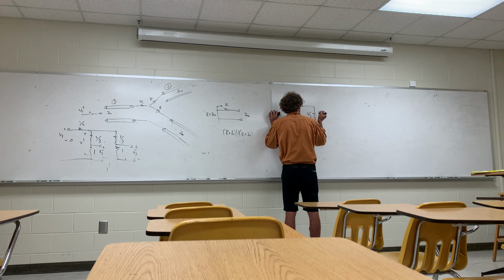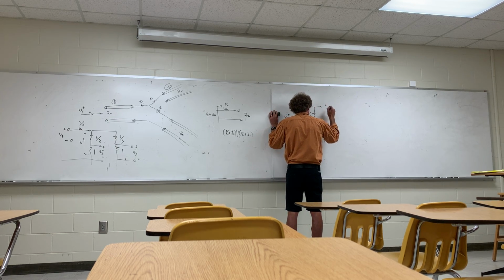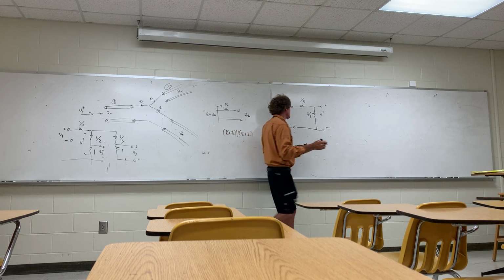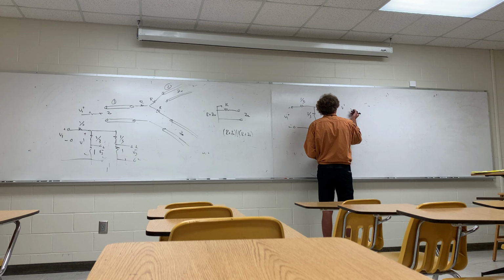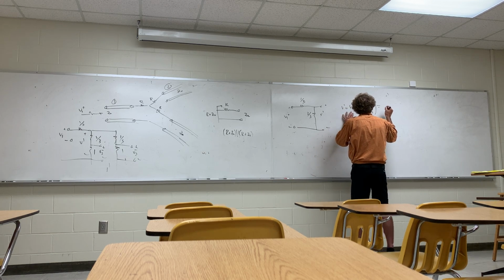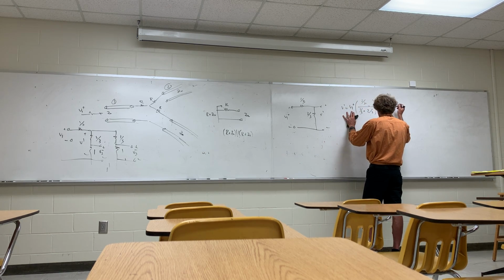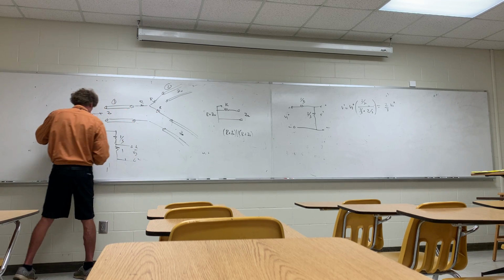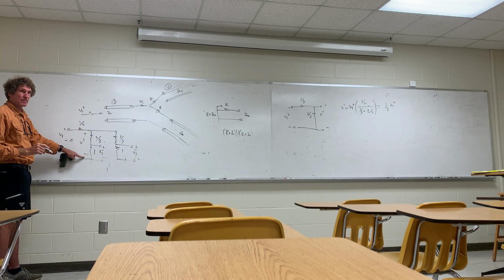Of an ohm, and I want this voltage right here. Everybody agree with that? So the voltage, when I look at V prime, that would be V1 plus times 2/3 over 1/3 plus 2/3, or simply 2/3 V1 plus. And that's the voltage right here. Can y'all follow me on that?